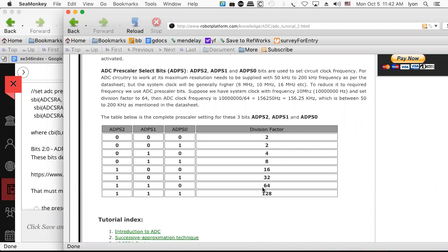That is a period of time which is not equal to your sample rate, right? It sounds like it should be, but it isn't. This is not the sample rate. What this is, because it's a successive approximation A to D converter, is the clock that goes into the register for the conversion. So it's not quite your sample rate yet. It's the clock rate that goes into the A to D converter.